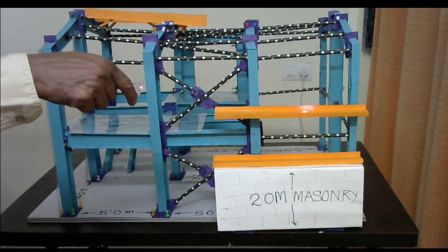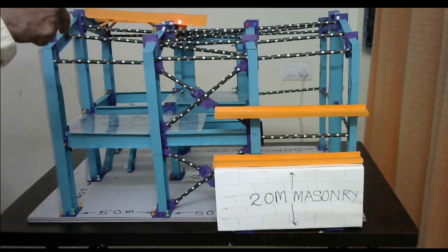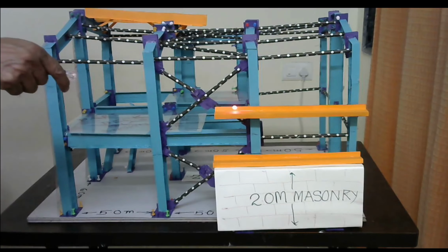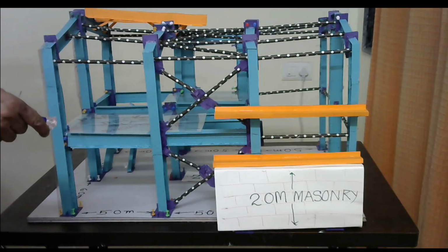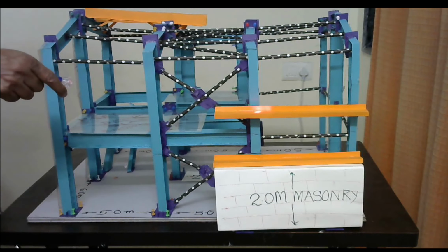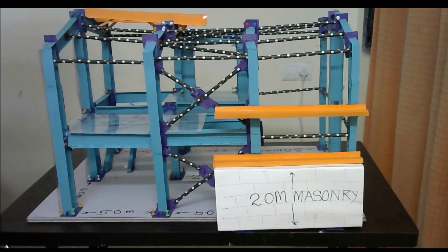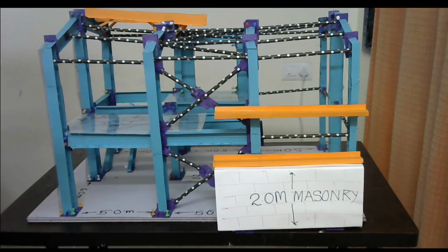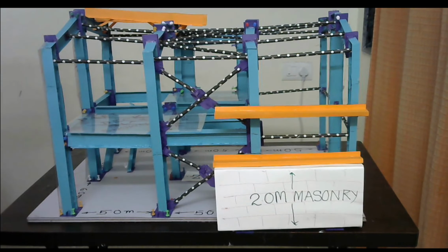For a PEB building, the flanges, the girts and the roof braces provide flange braces to the compression flange of the wall. Now in such a case, these girts or these purlins actually provide restraint to LY and LX. So in case of a PEB building which is provided with the flange bracing, the effective length parameter will be the distance between the flange bracing.